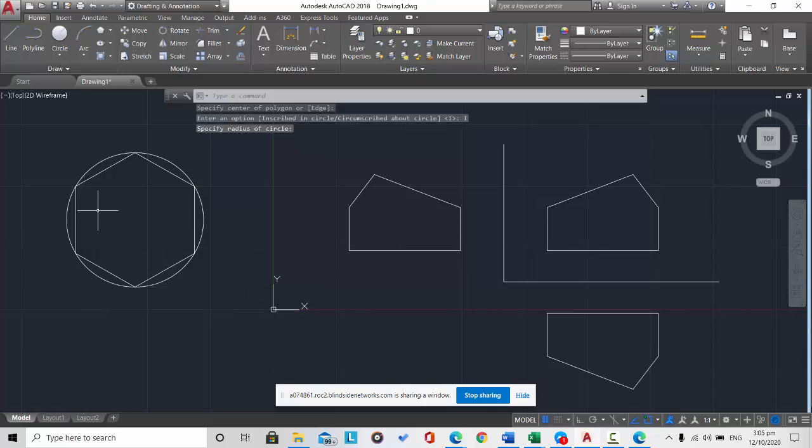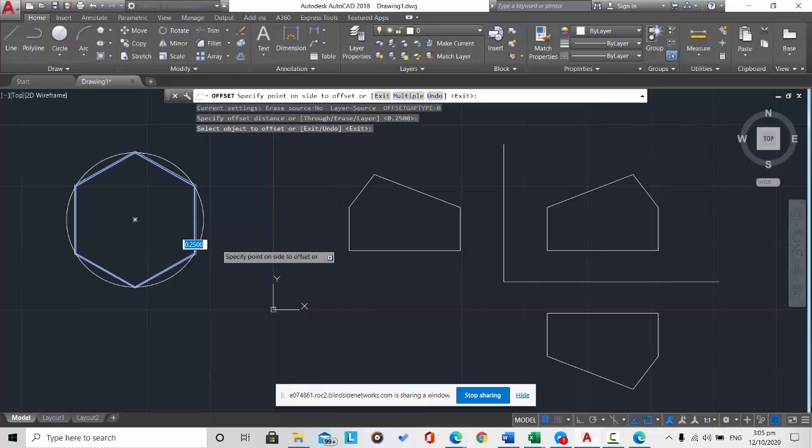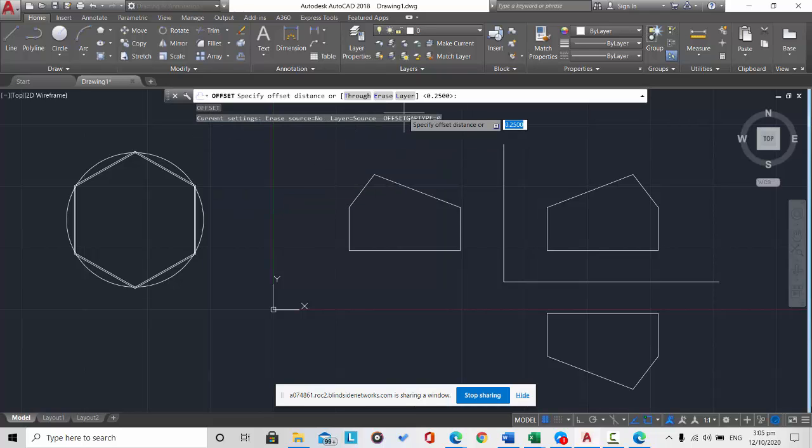So supposedly that is our drawing, for example. And then we want to offset, like 4.25, okay, enter, and then we click this as our object, outside. Let's do the multiple offset command, okay, wait, okay, and then click the object, click the multiple,